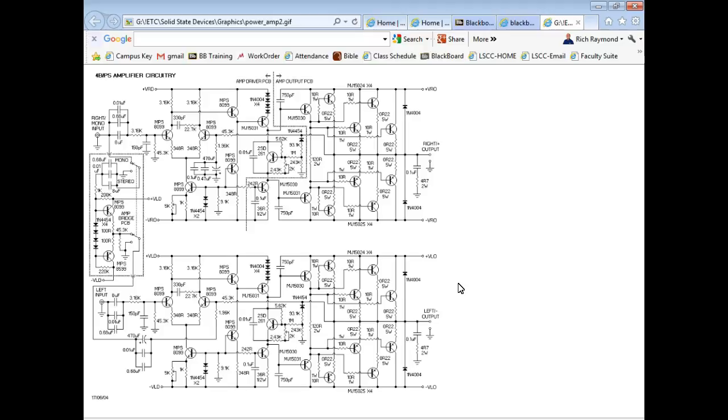Well, it's complicated, though, but it's just common emitter, common collector, common base. They're turned a little different. Here they're using 4 diodes. We'd have to, because they're going through a Darlington arrangement. So if I'm going through a Darlington, I've got to go 1.4, right? You understand? So here are the 4 diodes up here that are biasing these guys, ready to be turned on. Here are my outputs right here.